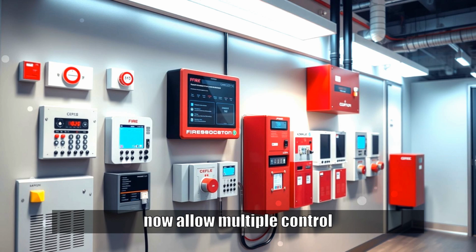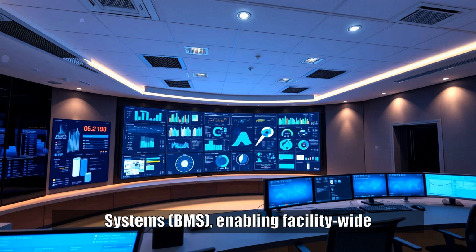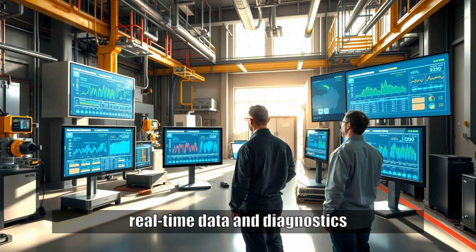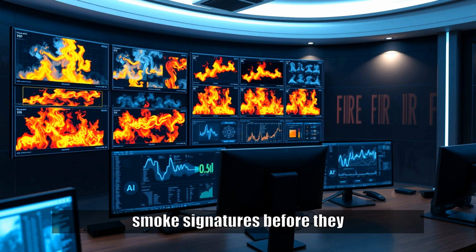Networked fire alarm systems now allow multiple control panels across different buildings to communicate with each other, providing centralized control and event logging. These systems are often connected to building management systems, BMS, enabling facility-wide monitoring from a single interface. Wireless fire alarms are gaining popularity in historical or complex buildings where hardwiring is difficult. IoT-enabled detectors can send real-time data and diagnostics to cloud-based dashboards, alerting facility managers instantly about system faults or environmental changes. Artificial intelligence is also being explored for predictive fire detection and pattern recognition, where systems learn from past data to detect unusual thermal or smoke signatures before they escalate.